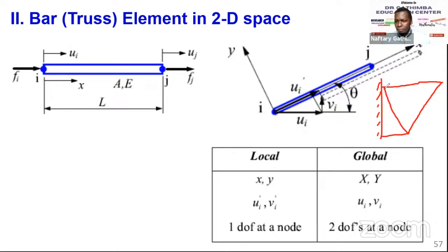Truss system, okay? If there is a load applied here, or a load applied anywhere else, maybe in this node you want to know the nodal displacement. Because of the applied load, as the structure deforms, you see in this node, which was initially here, we have both horizontal displacement, which is u, and from this node to this node, vertical displacement v. That's why we are saying there are 2 degrees of freedom at the global scale.